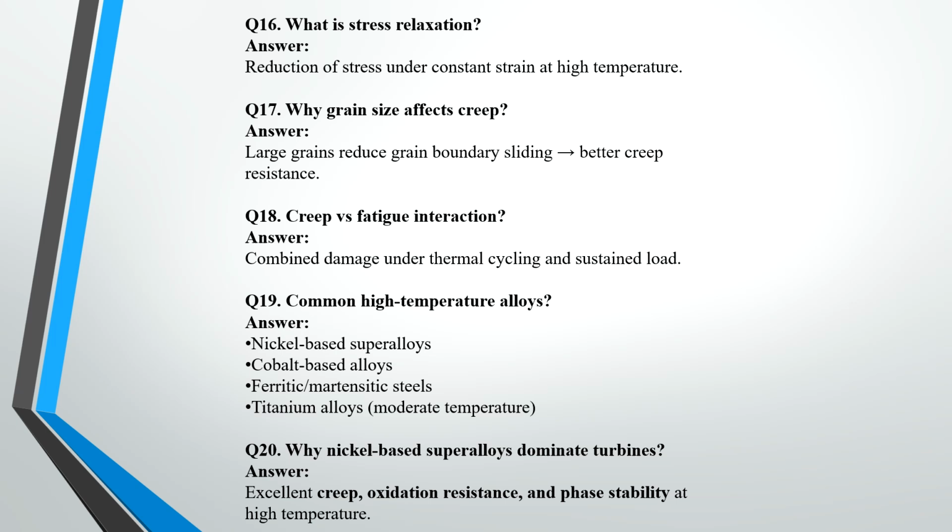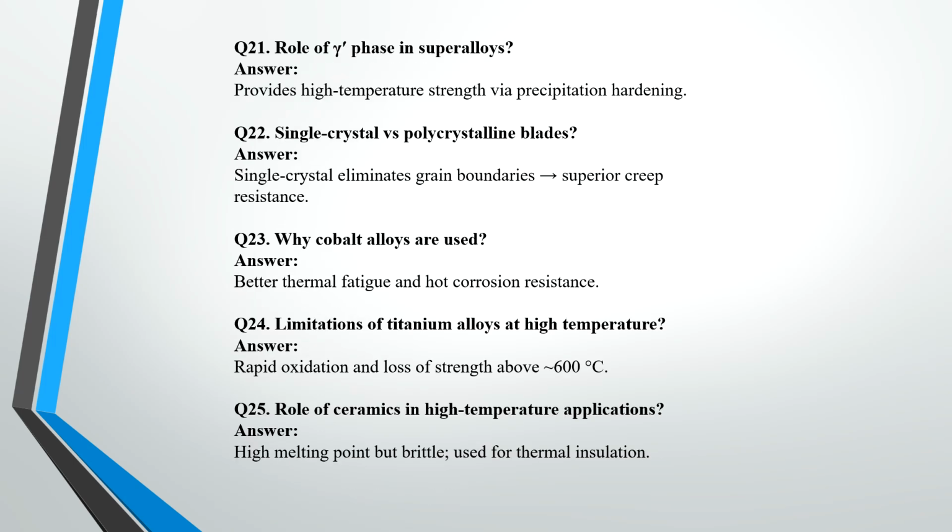What are the common high temperature alloys? One is nickel-based superalloys, cobalt-based alloys, ferritic or martensitic steel, and titanium alloy at moderate temperatures. These are some of the alloys we use in very high temperature applications. Why do nickel-based superalloys dominate turbines? Because they have excellent creep and oxidation resistance and phase stability at high temperature. That's why we use nickel-based superalloys in gas turbines.